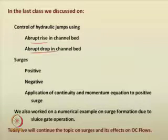We also discussed surges, what is meant by a surge, the positive surge, and the negative surge. We also applied the continuity and momentum equations to analyze the positive surge, and worked on a numerical example on surge formation due to sluice gate operation. So, today we will continue the topic on surges, and with today's lecture we would like to wind up this module as well. We will discuss surges and their effects on open channel flows.